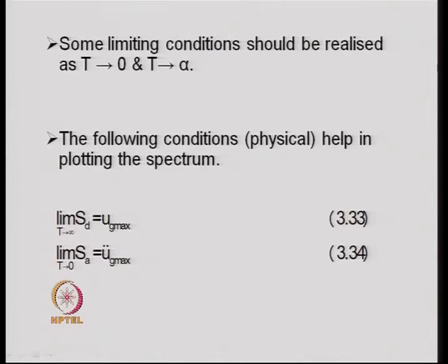So, taking advantage of these two relationships, we are able to plot all the three quantities, that is the SD, SV and SA, in a single plot having the logarithmic relationship, or in other words a special kind of log graph in which we have four ordinates.